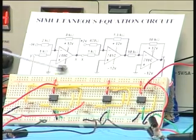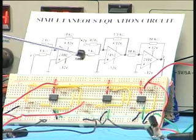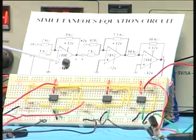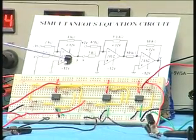Once I wire the circuit with all these values, if I measure the voltage here, that will give me the value of x, and if I measure the voltage at this point, I will get the voltage y corresponding to the solution x and y of this equation.